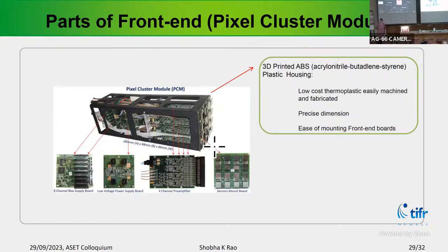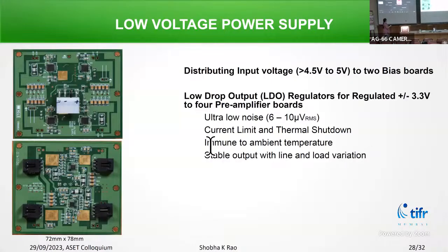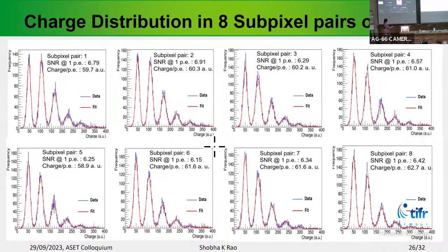When you are doing very fast pulses, after one pulse has gone through and the second pulse comes, the input transistor, the input junction, hasn't come to the base level. So you have to do what we used to call pole zero correction. That is an active way of bringing it to zero. Then you don't get fluctuation in the zero output. So I saw that their correction is poor.